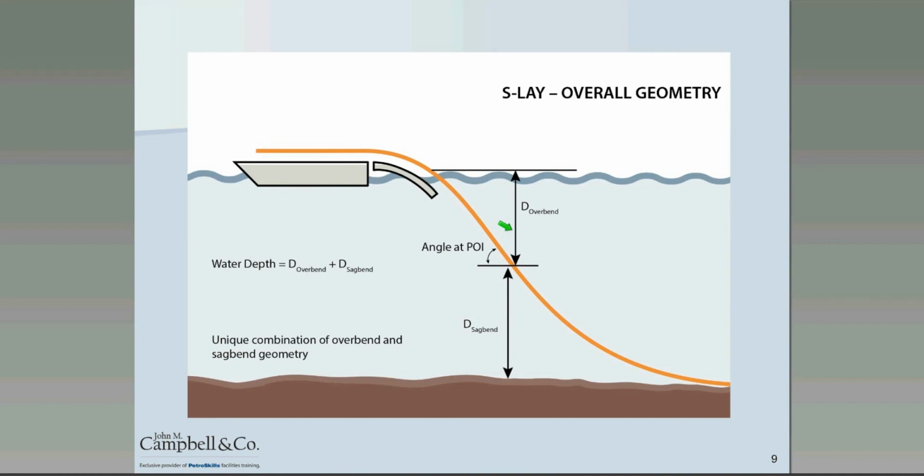Also, the tension is usually applied to the pipe after several of the welding stations have completed their work. You have to get at least a certain amount of the welding completed before you have adequate metal area in there to take the tension and the related axial stresses that are going to be placed in the pipe to apply the tension.